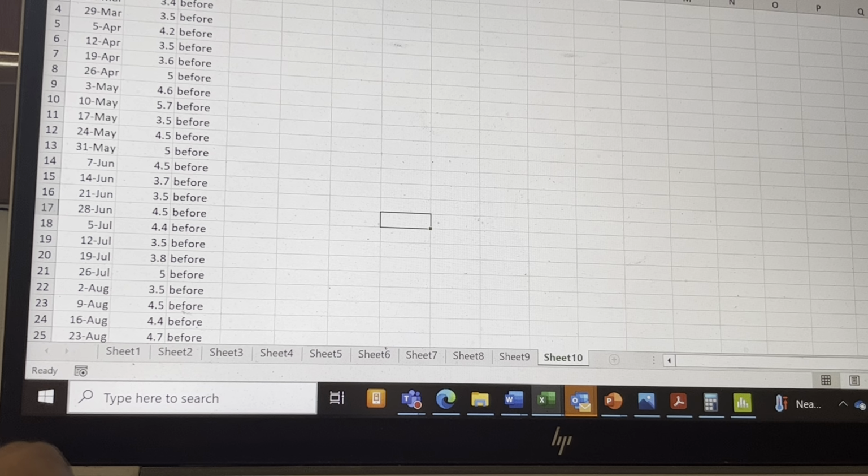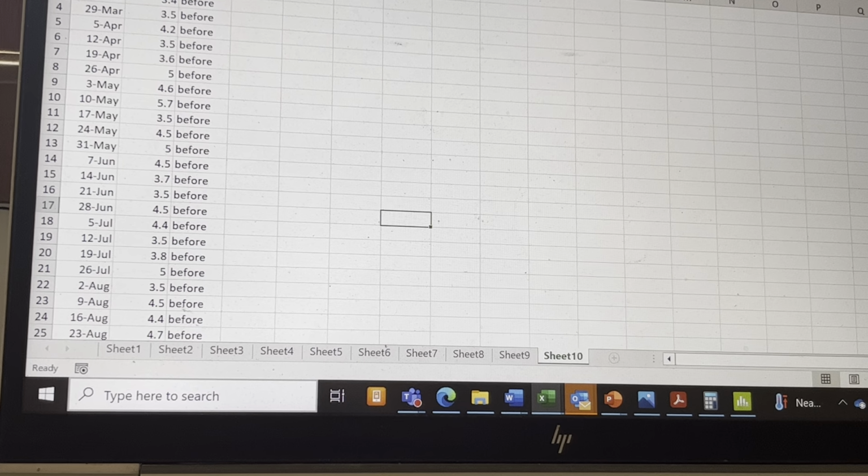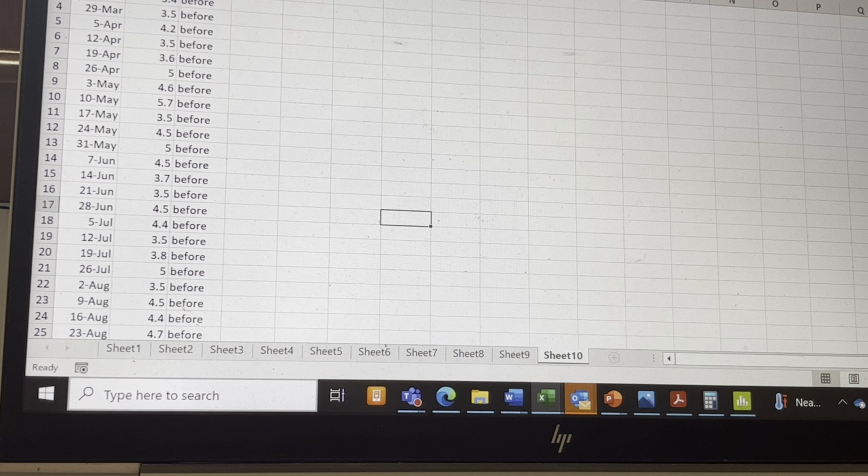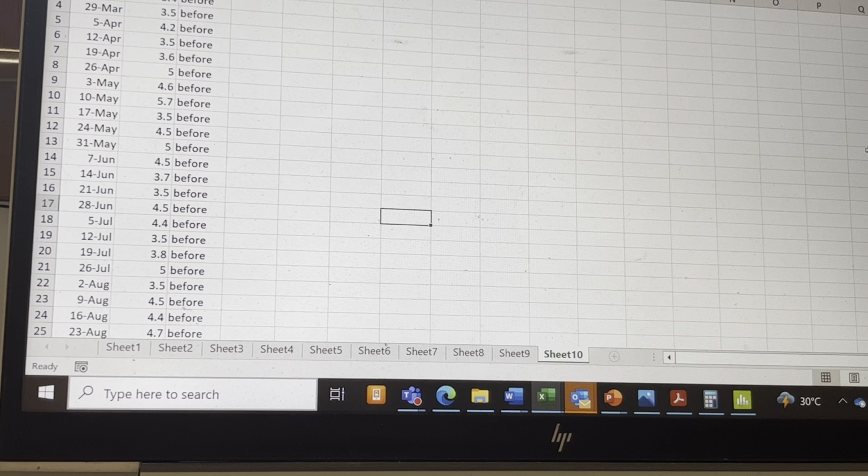So basically, I showed you how to work on the P chart, NP chart, C chart and U chart. Doing a control chart is not a very difficult job because the process of making the chart remains the same. The most difficult thing is how to collect data meaningfully from the process. You have to define the variable very smartly, collect data, and then do the right chart.